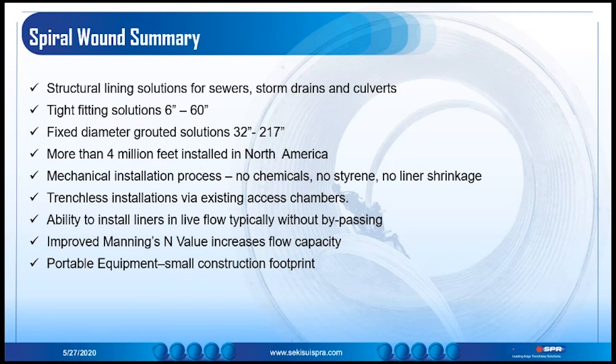Okay, thank you, Chris. Here's another question. If a large storm is coming and normal or high flows need to be reintroduced to the pipe, what measures need to take place to ensure the liner is not damaged if it is in the mid-pipe segment? When the high flows are one of the obstacles associated with the project, the SPR contractor will install the first bulkhead in a grouted application that will hold the liner in place during that event. The equipment will be secured in place, and then depending on which of our tight fit groutless products are used, the liner can be installed and left in place while the event occurs, with winding to resume afterwards. In some cases, the installer may choose not to install on the days when there are high water events that might occur.